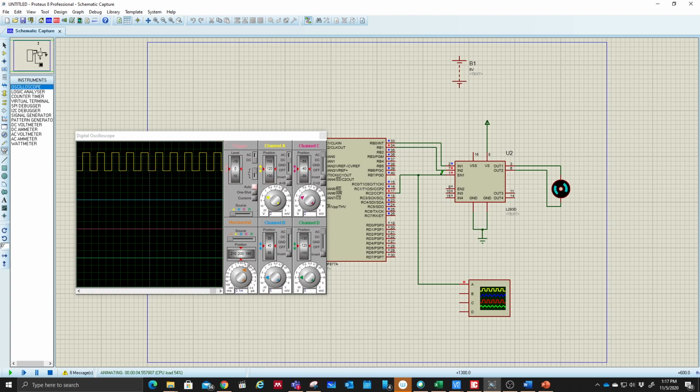So without these CCP pins connected, you cannot rotate the motor with a driver, because it needs to be driven by these two H bridges. Consider the H bridge, and this is your input for the PWM. So you can control your PWM accordingly to the set duty command just now. Okay, so let's try another thing.